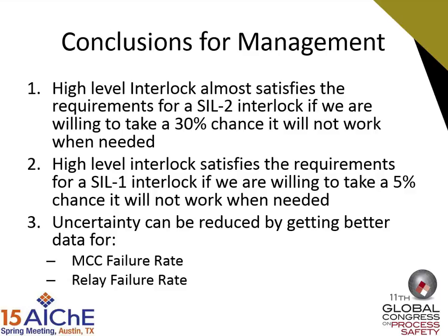Conclusions. If you really want to do what we've got here, there's a 30% chance that it's not going to work when needed. If you want to make sure that it'll work, then I'm going to have to say this is only SIL 1 and it doesn't satisfy our requirements. If I want to get it better, I've got to buy some better equipment. That is the MCC, I'm going to have to change it out. That's the switching equipment. I'm going to change the relays out.